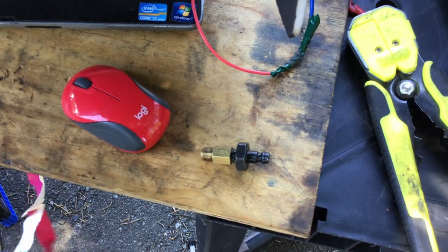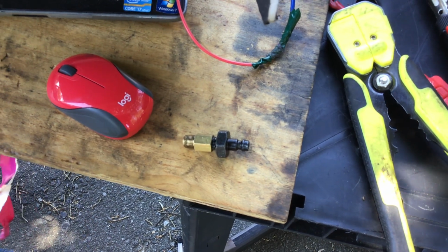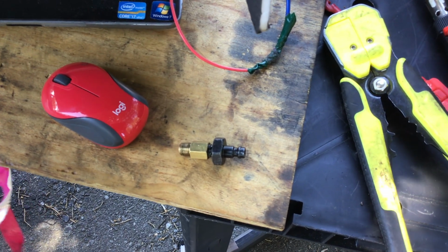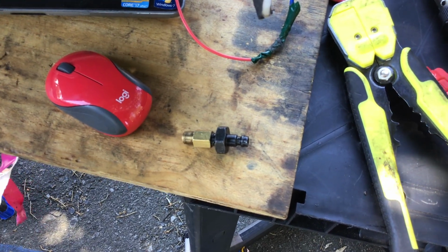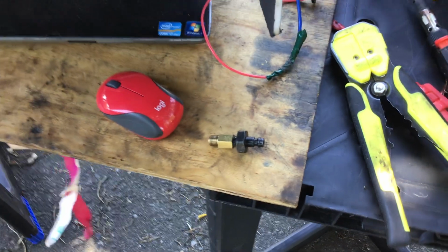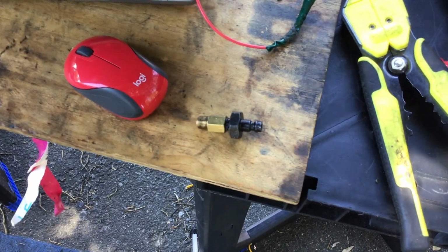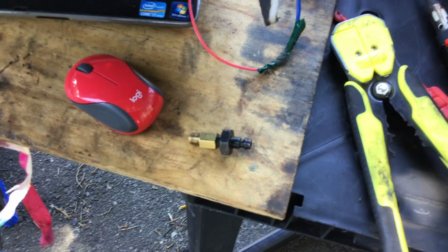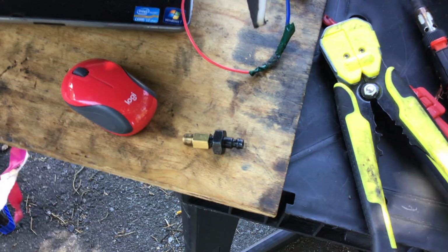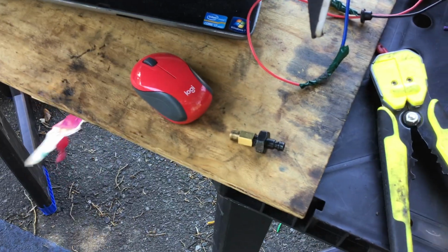But be very careful with this testing methodology. I did take it down the road. Everything has been scoped and recorded, and I'll show you the scope capture. But this is nothing we want to be taking on a long road test. Be careful of your routing. It's really important. I always felt safer when the scope was on, because I could actually look at oil pressure. If that thing ever took an abrupt turn down, my hand was right on the key to shut it off as quick as you can. We don't want to lose oil pressure.